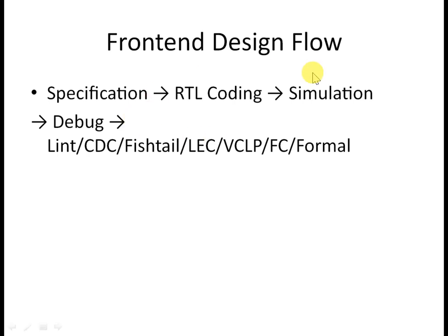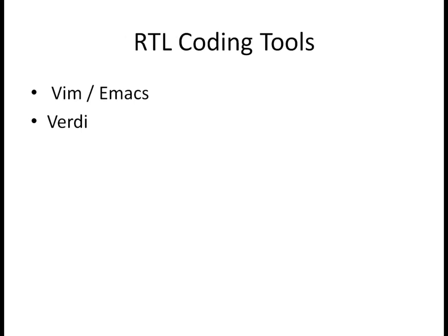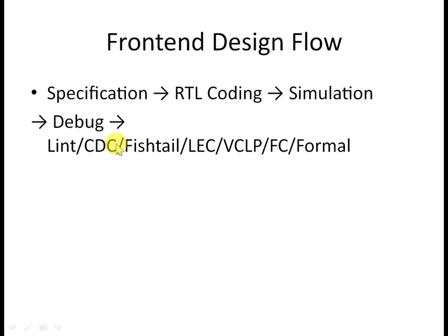So these tools are used in mostly all the companies in the industry. We'll be discussing them one by one with a few rules now. Let's start with lint. As I already mentioned, lint is a tool used for checking whether the RTL is following the design rules and coding guidelines.